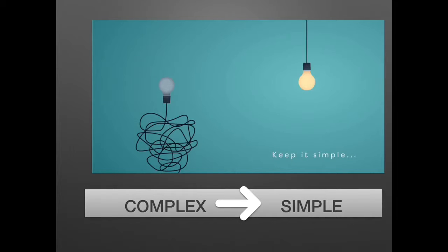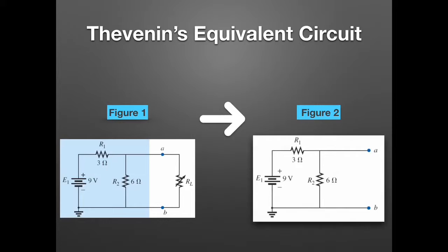We want to simplify the circuit seen in Figure 1 to determine the Thevenin's equivalent circuit. So step 1 to do this is to remove the variable resistance from the circuit as shown in Figure 2. We will input this at the end of all the steps. Once simplified, we need to calculate the Thevenin's equivalent resistance.